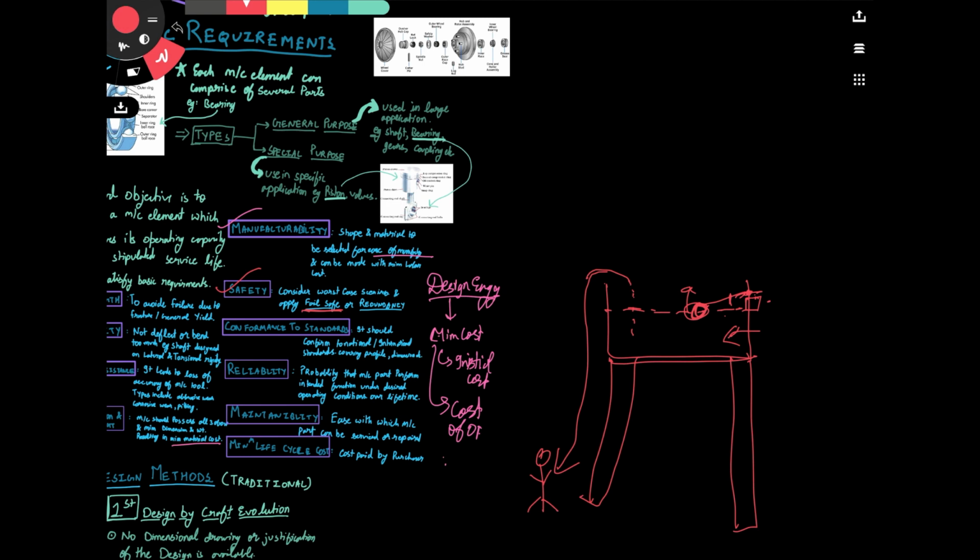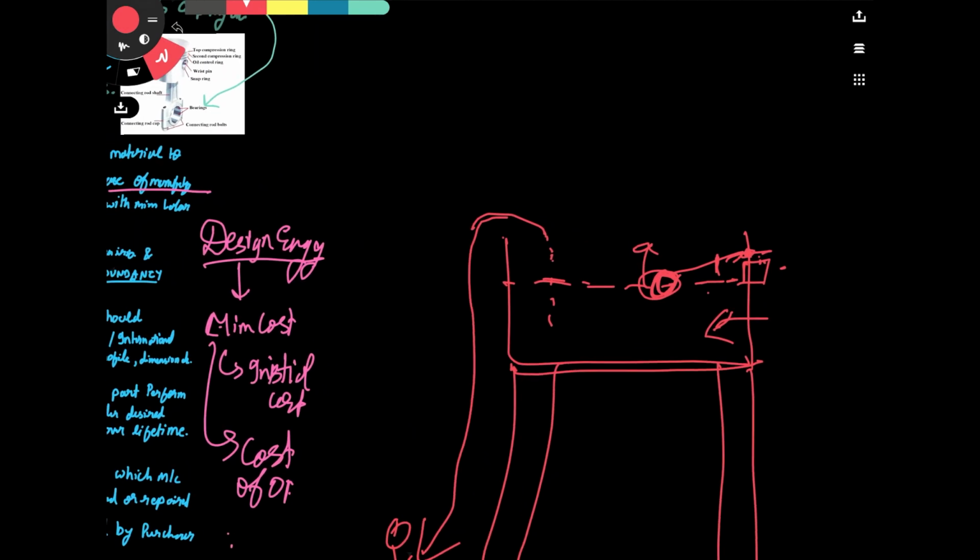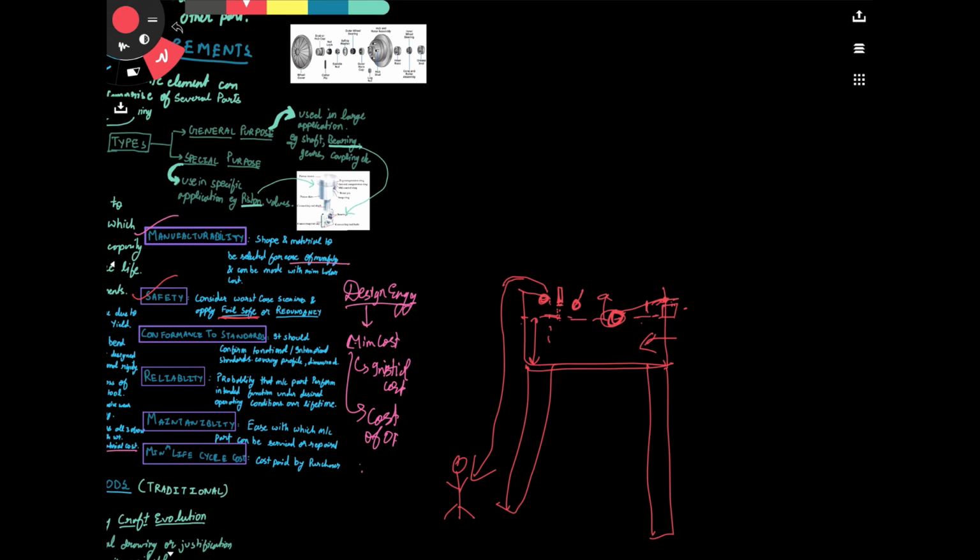So what the engineers at that time did was, this was the maintained level, and they added a few more floats, a level switch, and an ultrasonic electronic device. So even if this float fails, they have these things working side by side. Let's say just two things: one extra float and one electronic ultrasonic sensor, to know the distance.